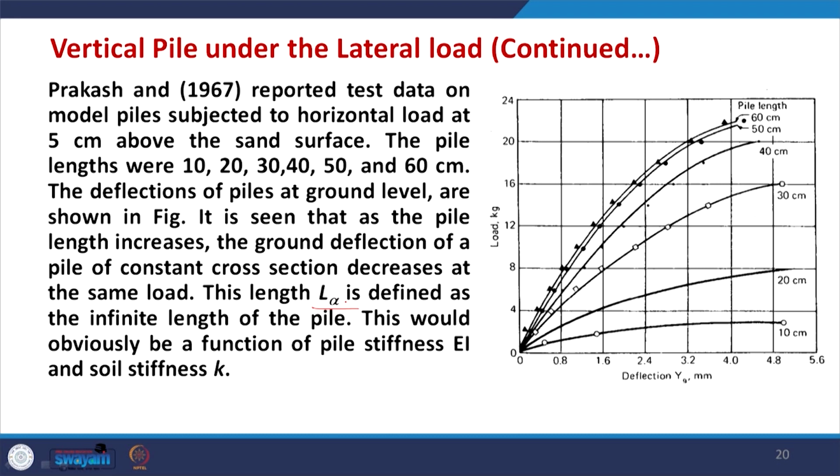Prakash and Saran in 1967 reported test data on model piles subjected to horizontal load at 5 centimeter above the sand surface. The pile lengths they considered for the testing were 10 centimeter, 20 centimeter, 30, 40, 50 and 60 centimeter. The deflection of the piles at the ground level is shown in this figure.